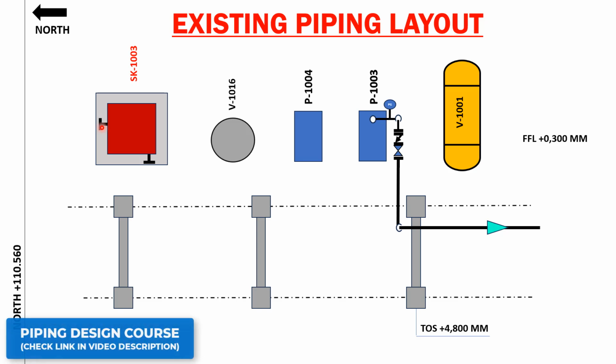Generally there will be some concerns, and those concerns will have to be discussed with the vendor, and only then will it be finalized. Both the vendor and yourself have to coordinate and finally arrange the nozzle orientation. Nozzle orientation is based on different factors. One of the factors here is suction. Suction in the sense you have to provide some supply. So you need to have a provision for the truck to come over here. Here we have an open space, so the truck can come and put a hose connection and connect it.